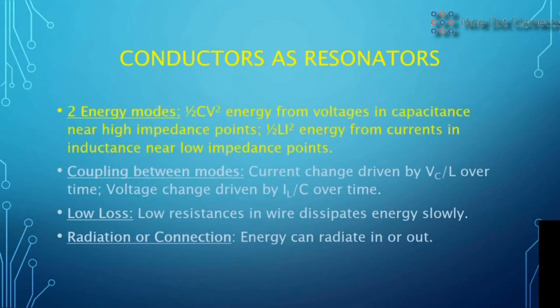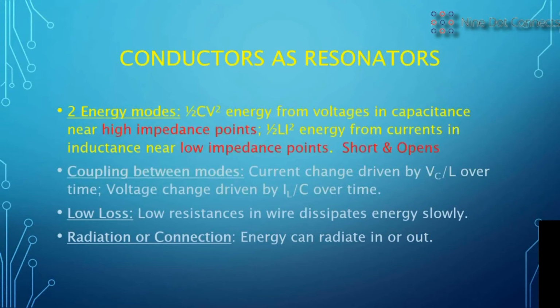Well, they have 2 modes of energy. Because there are high impedance and low impedance points due to shorts and opens or low impedance drivers and high impedance receivers, at the high impedance ends they have a significant voltage change, and they also have capacitance arising from that, so they can store a significant amount of 1/2 CV squared capacitive energy. Also, at the low impedance points, where a lot of current flows, they have an inductance arising from the magnetic field. Hence, they have a lot of 1/2 Li squared inductive energy in them. So yes, they have two forms of energy.